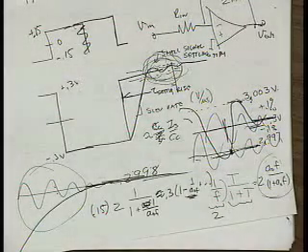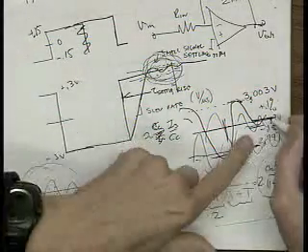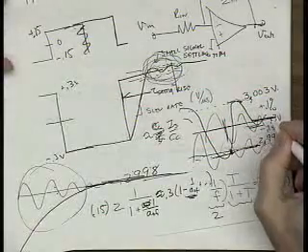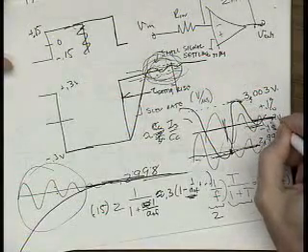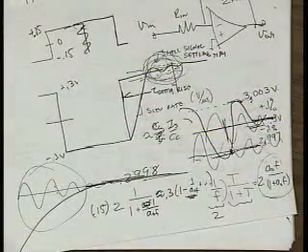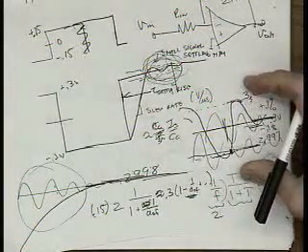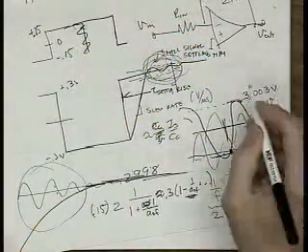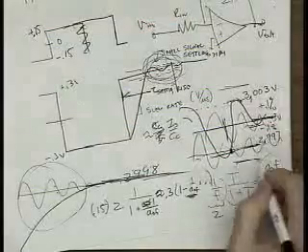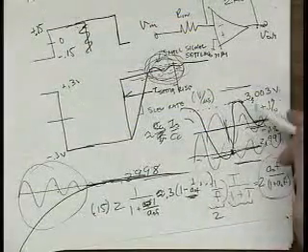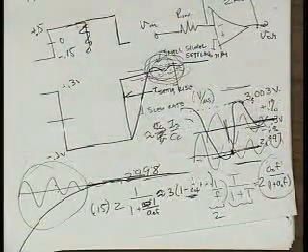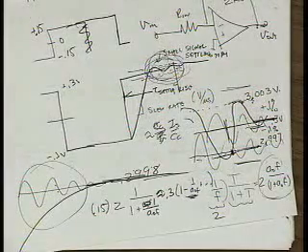Static settling time doesn't mean anything. Static settling value is where it finally settles to after a long period of time. If the static settling value is outside the plus or minus 0.1%, the thing will never settle. You'll never meet the settling time. The settling time will be infinite.